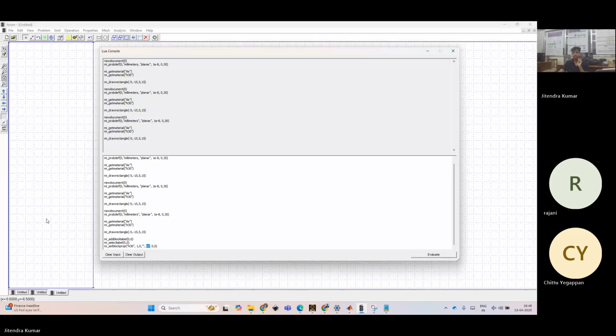Next is 90° or something. So it is a magnetization angle. How much magnetization degree you could give. So here, if we are giving 90°, which means along the plus y axis. So magnetization should be from the bottom to top. So this should be the magnetization orientation, right? And the next is again related to circuit or number of turns, and since this is a permanent magnet, it should be 0. Okay. Any doubt here?